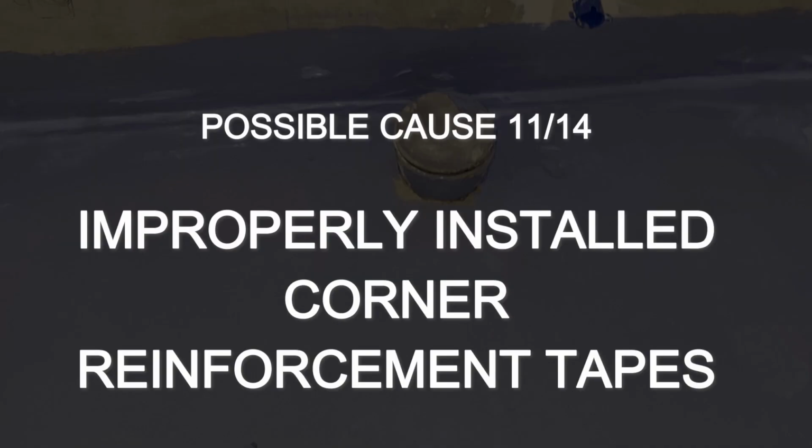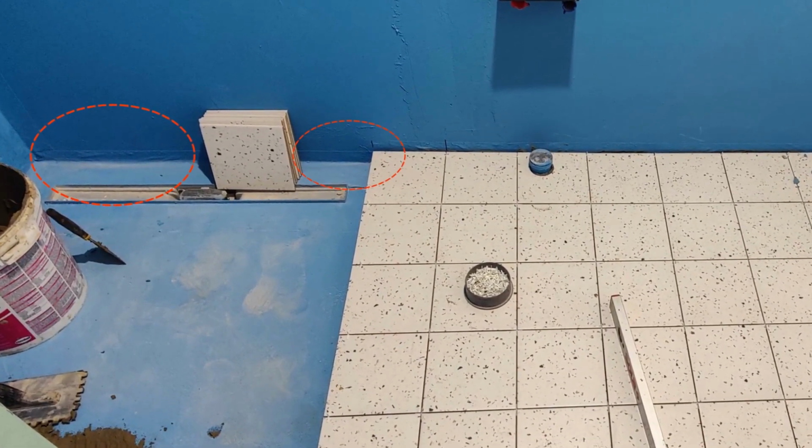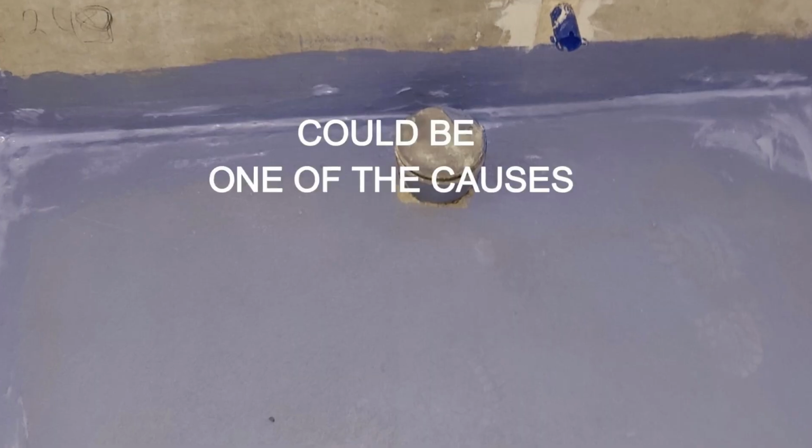The 11th version. Reinforcement strips were improperly installed in the corners or not installed at all in some places. Corners are sensitive areas because different planes meet there and deformations are possible. In one area that was opened up for us, the tape was present, but in other construction photos, there were visible bubbles and unevenness, and in the work documents, their installation was not recorded everywhere.